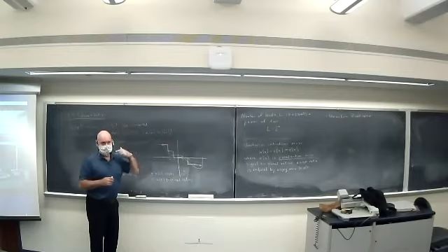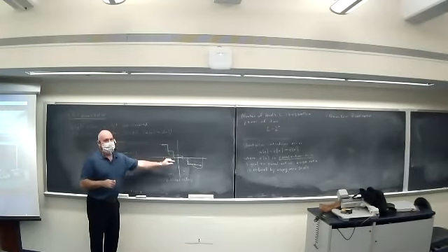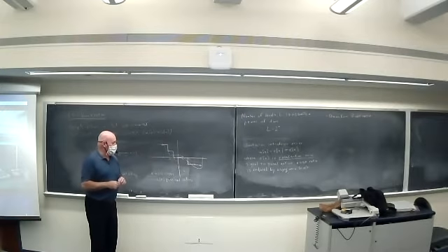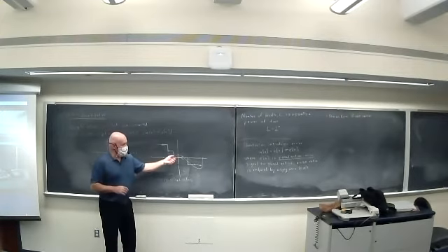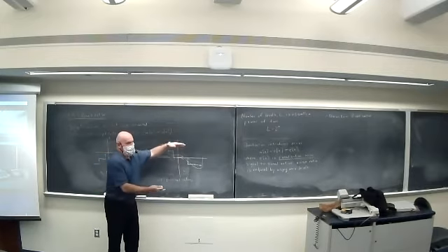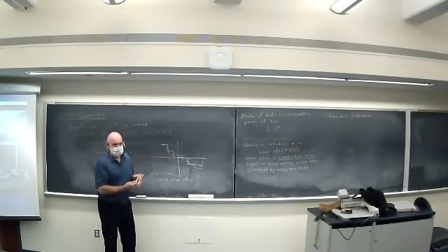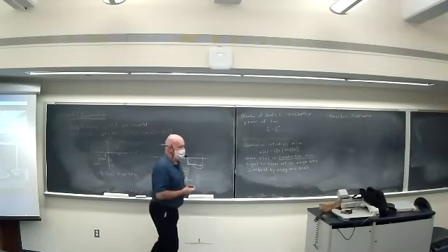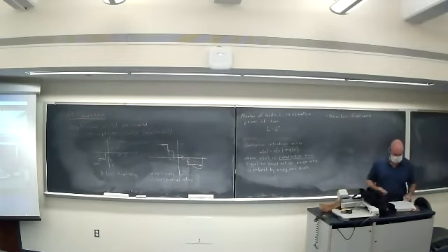So this is a psychological or acoustic effect: you can hear the quantization error at low amplitudes. So someone had the bright idea, well, what if I use smaller spacing for lower amplitudes, and larger spacing at higher amplitudes? I still have my 256 levels, but they're much closer together at lower amplitudes than higher amplitudes. I can get better sounding audio. Okay.